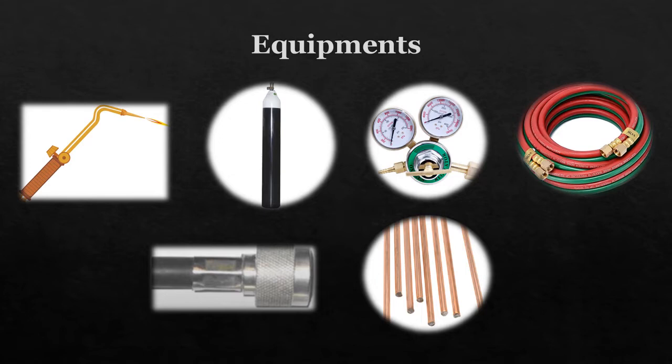For proper burning of fuel, an appropriate amount of oxygen is required. This oxygen is supplied by an oxygen cylinder. Then the other cylinder is the fuel gas cylinder. The gas cylinder is filled with either oxyacetylene gas, hydrogen gas, natural gas, or other flammable gas. The fuel gas selection depends on the welding material.